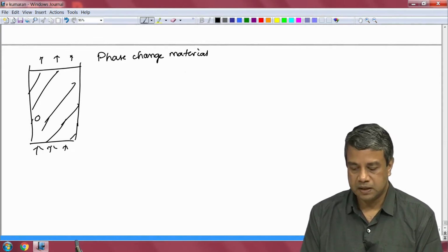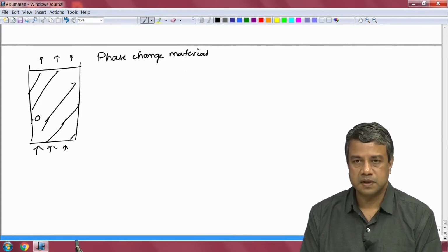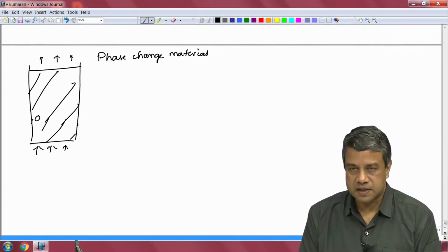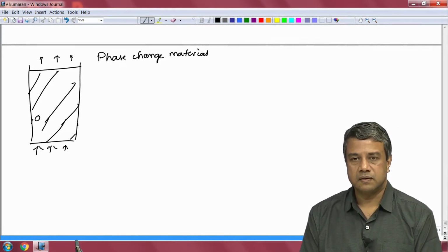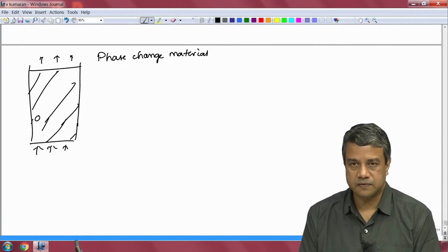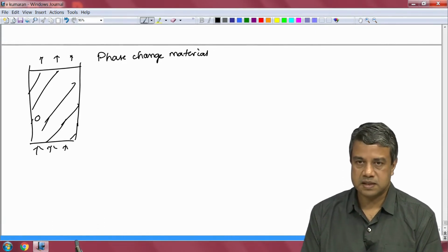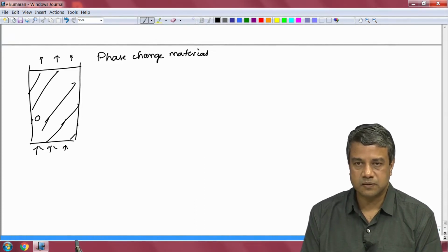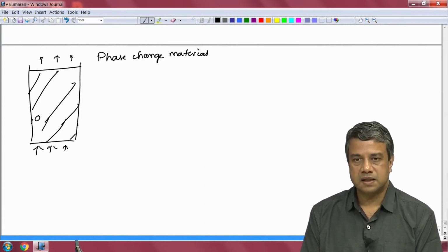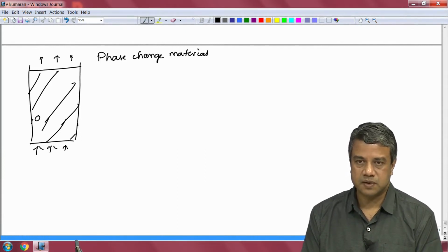So, in heat recovery processes, for example, you could have this phase change material in a packed bed, and you could store the energy by passing hot fluid through it, so that it melts at a particular temperature, and then heat a cold stream such that the heat transfer from the wax to the cold stream will freeze it. So, basically you are using this material to store latent heat at that particular temperature.